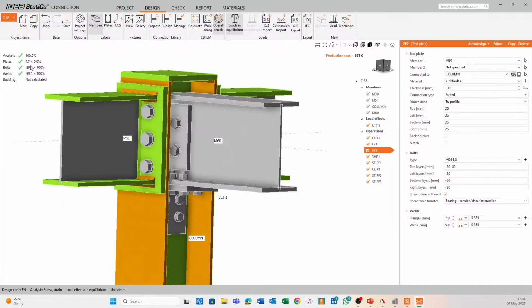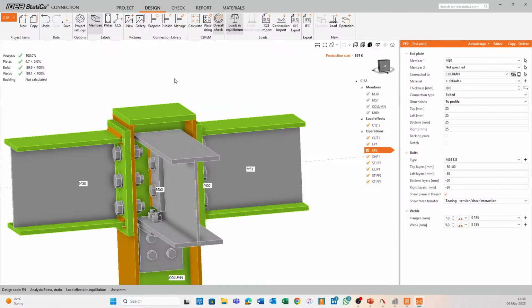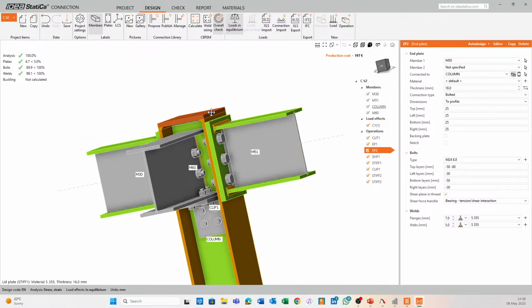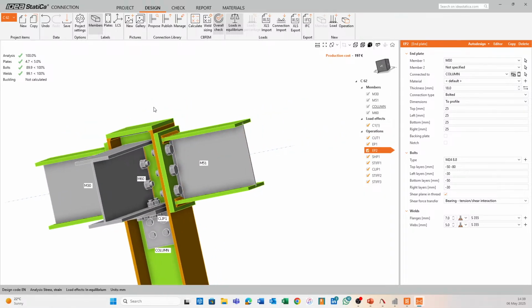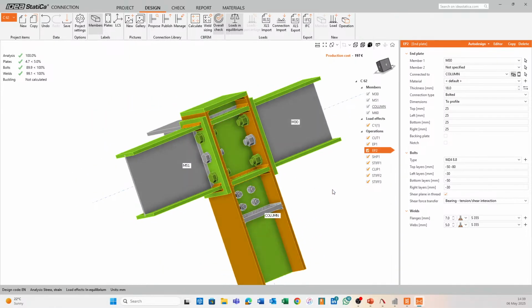Whereas our first, if you remember, our first plastic strain value was at 1,366.7%. And we got it down just through the process of changing the size of bolts, changing end plate thicknesses, changing weld sizes, and modeling in stiffening plates. We actually got it down to 4.7%, which is phenomenal. Honestly, I was not that optimistic that we would get that value, but really amazing.